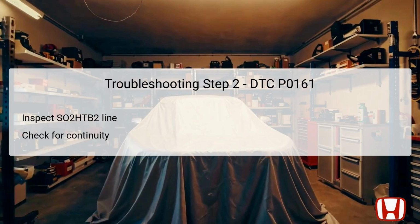If any issues are detected, these should be addressed immediately. Repairing any damaged wiring or connectors will be crucial to restoring proper function. It's important to ensure any connections are secure and free from corrosion, which could also lead to intermittent issues.